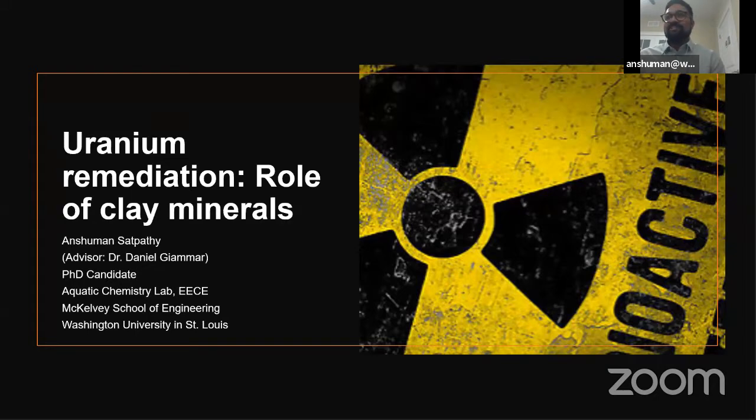Concrete is not a good packing material in those environments, because the spent nuclear fuel is going to release a lot of heat, and then the concrete will crack. So good confinement is using a metal which is more malleable, and then confining with clay, which is thermally stable. It expands when it swells with water, but it does not develop cracks if it is moisturized properly. So concrete, I won't say is a good material.